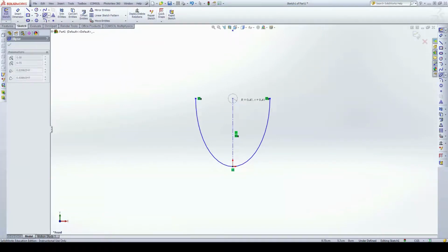So go ahead and click on it, and you're going to go down until it says stay on the center line, and then you're going to go till it says 0.8 centimeters. Since the wall is going to be 0.8 centimeters thick, and the outer wall was 3.3, this one will be 2.5 centimeters wide.